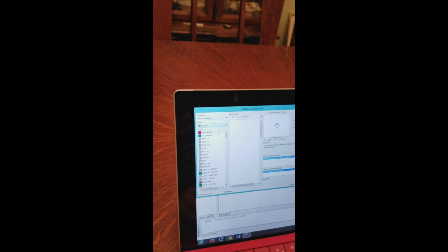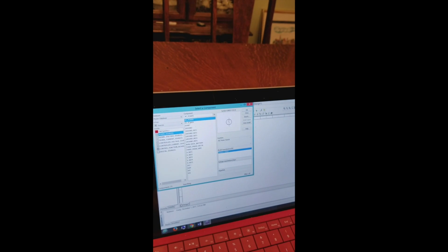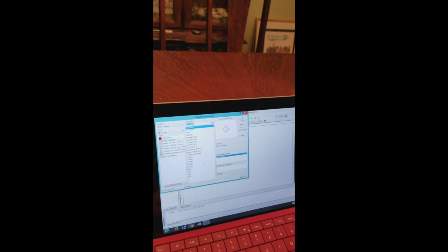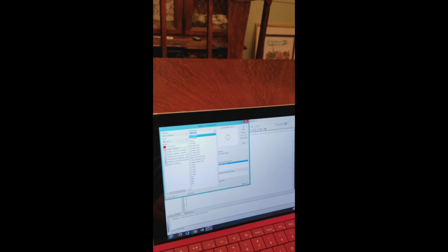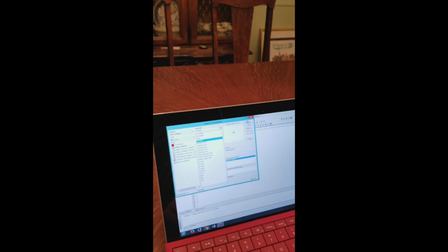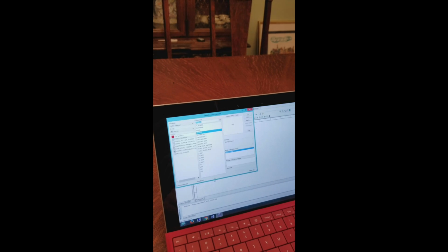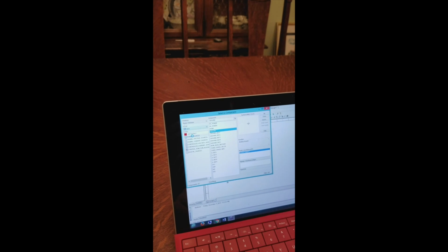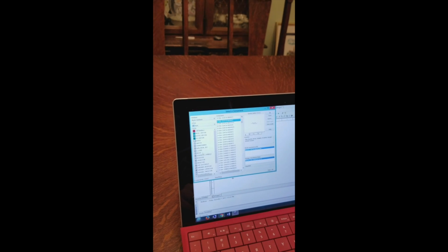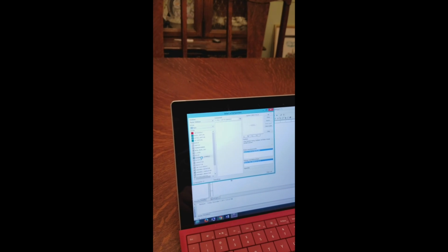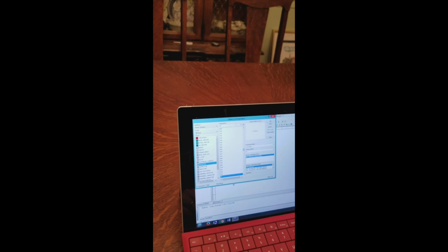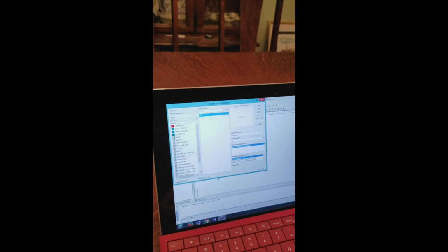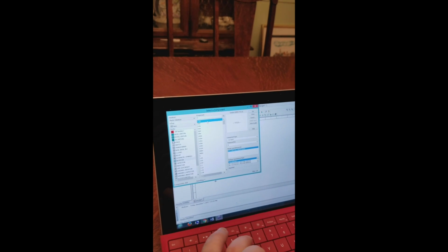So first thing I'm going to do is jump in here, go to sources, grab our AC power source, place it on the board. While we're over here, we're also going to grab our ground and put it down here. We'll go over now to our basic category. I'm going to grab the resistors that we need. So the first one is our 1.5 k ohm, not 11.5 k ohm.